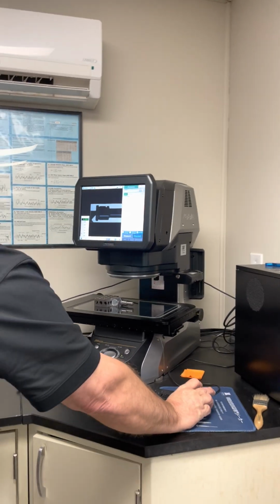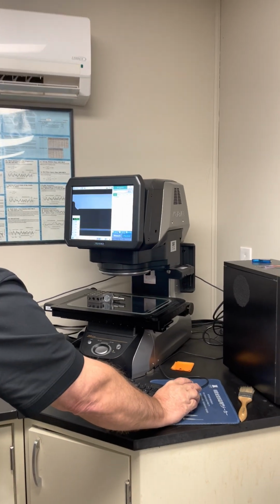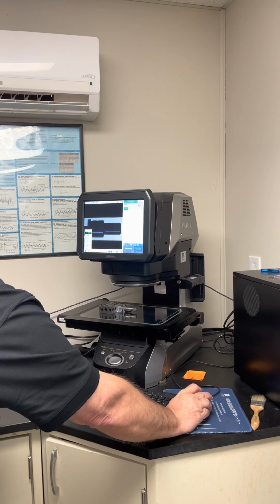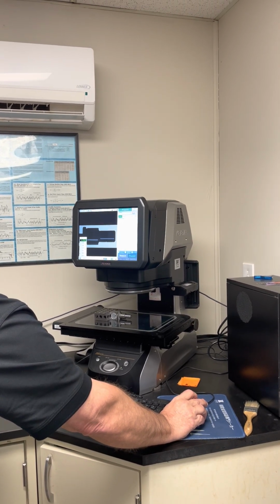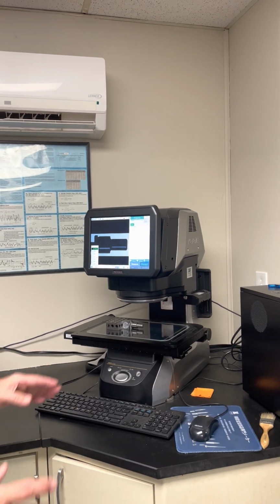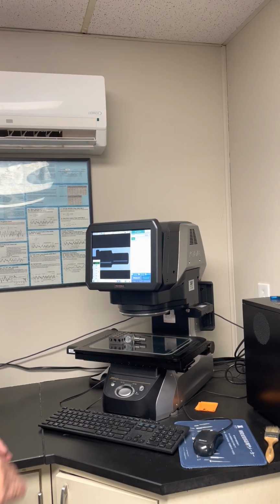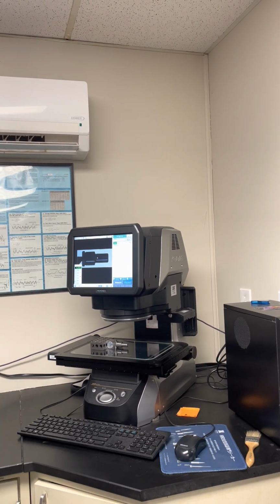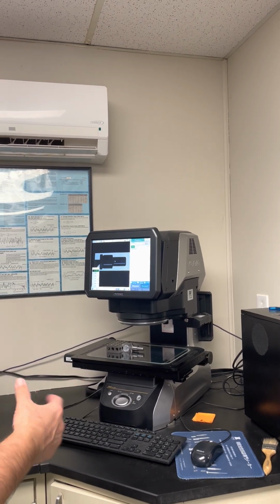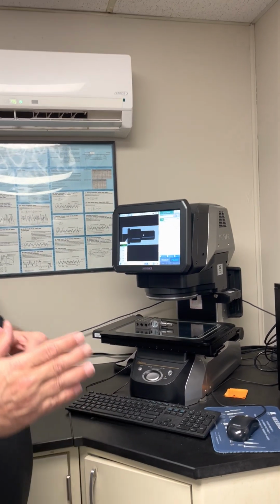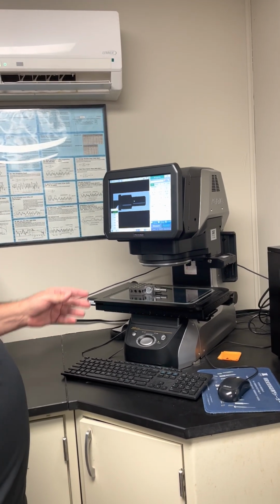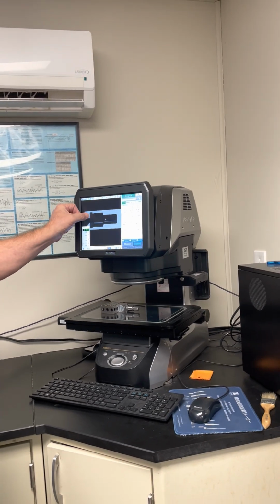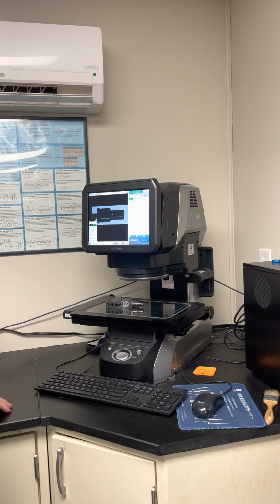All right. So now what we have is basically all this edge here, this edge, this edge, this edge, these are all in focus because they were all basically at the same height. Okay. So before I start, one of the things that I like to do as well is throw in a center line to begin with. I want to create a datum structure. The best way to create a datum on most parts is going to be a center line, and then typically either the end of the part or the front of the part, something of that nature.